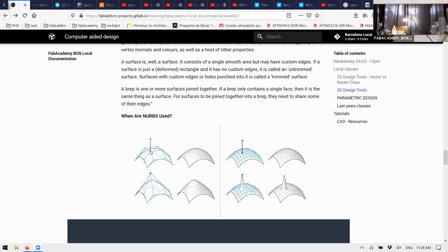So what is outside and touching the normal of the table is outside the model. If I'm able to go inside and no normal touches me, I will be inside the table. That's how a 3D model works with a mesh. What happens? A mesh, that is something that we will see in two weeks in 3D printing. A mesh can be wrongly made. It could be defined by the points, perfect, but the surface could have the normal pointing the wrong way. In that case, it's a broken mesh.